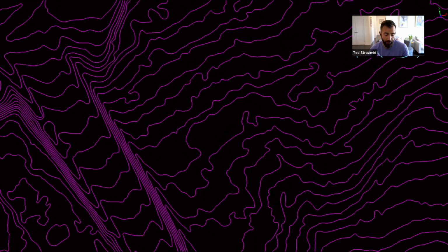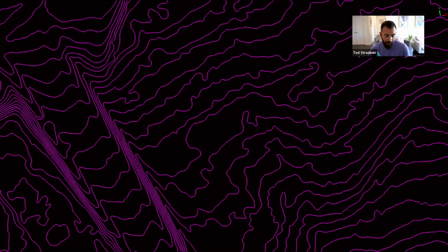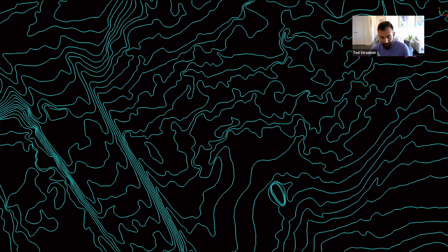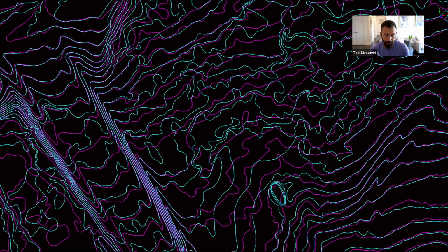There's a road on the left there. And in the LiDAR data set, the purple, you can see those contours at that edge, very, very uniform, very consistent throughout. But then on the photogrammetry data set, you see some weird stuff happening with these contours, some very short ones, some peaks in areas that probably aren't there. And so it's all about that consistency across the entire survey that really matters.